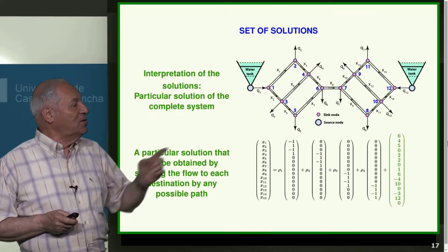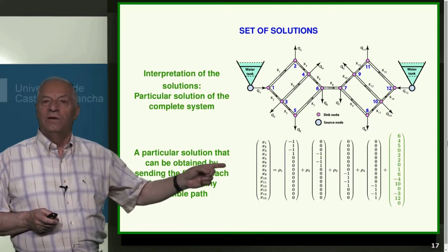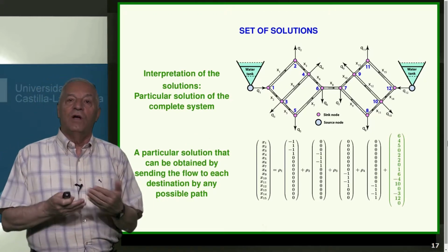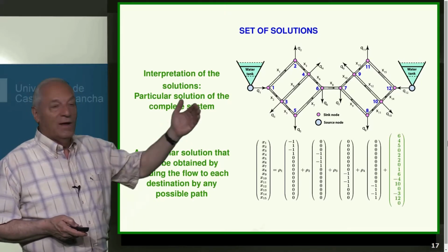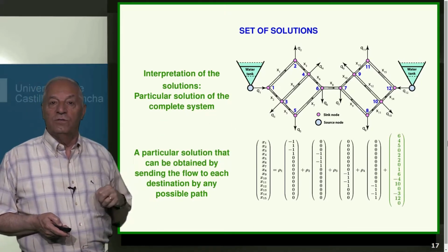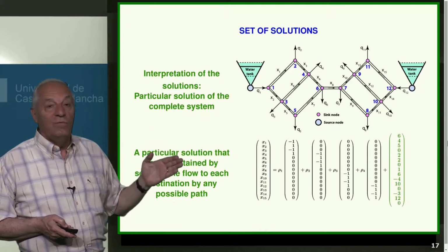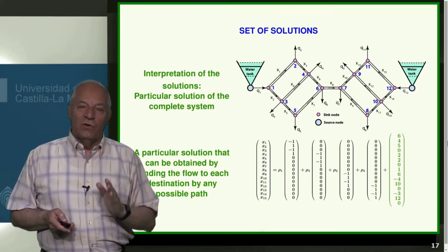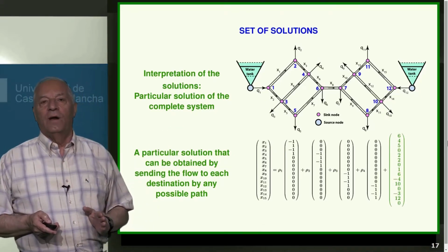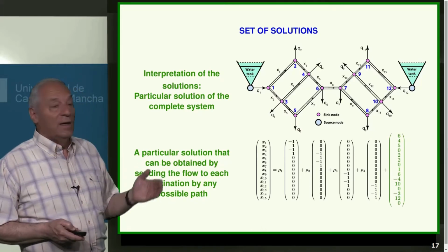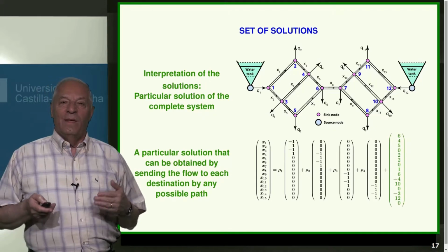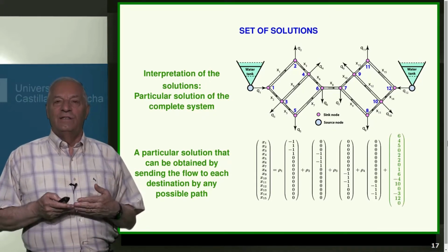For example, if I have to send 5 units of water, and there is a deposit with this amount of water, the path goes from this deposit to the point, and all unknowns we find take positive or negative signs, depending on the path and the unknown directions. That's what we do. We repeat it for all consumption points, and then we add all flows for all points' paths, and we get the particular solution.